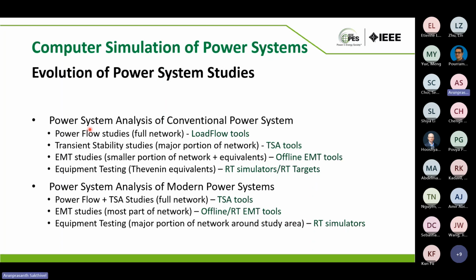When it becomes transient stability analysis, a major portion of the network was modeled in TSA tools. And when it comes to EMT studies, only a selected portion of the network was simulated. The rest of the network was simulated as an equivalent, and often offline EMT simulation tools were used.